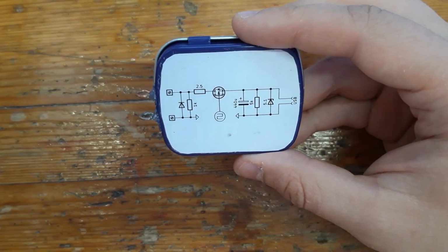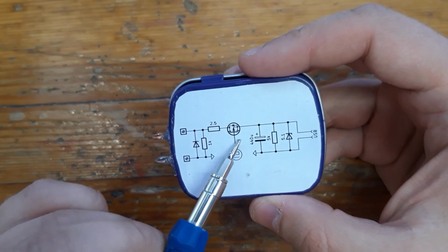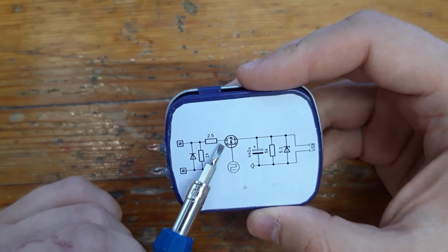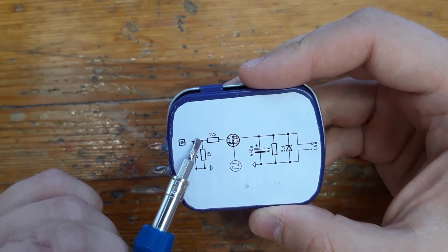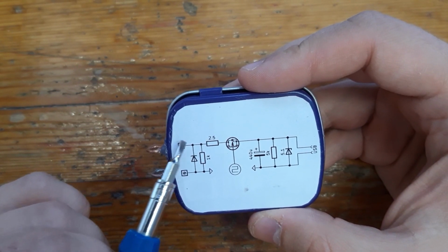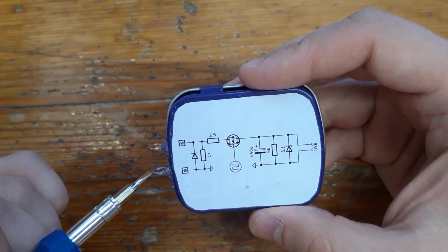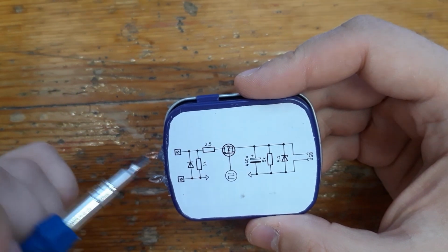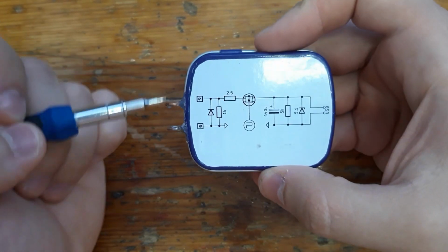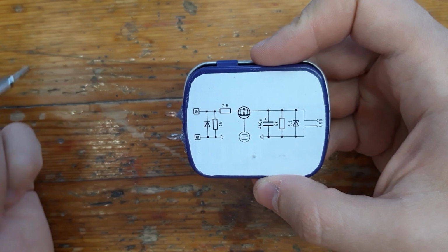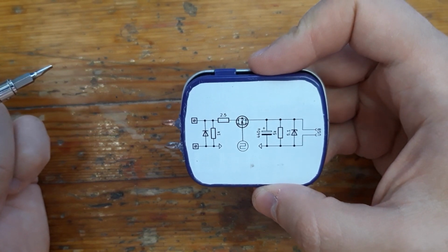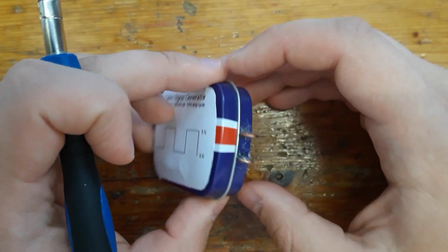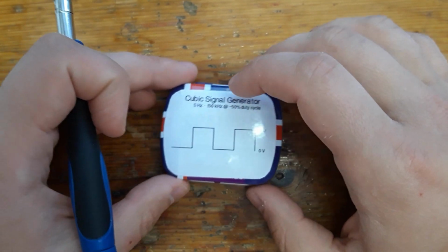In the configuration I have, there is just this p-channel MOSFET that amplifies the signal, and it feeds charge into this output line, and the charge has nowhere to go but this resistor and the connected load. A bit of a fail, I know, but I learned a lot. After all, learning the things is the reason why I decided to make one instead of buying it.